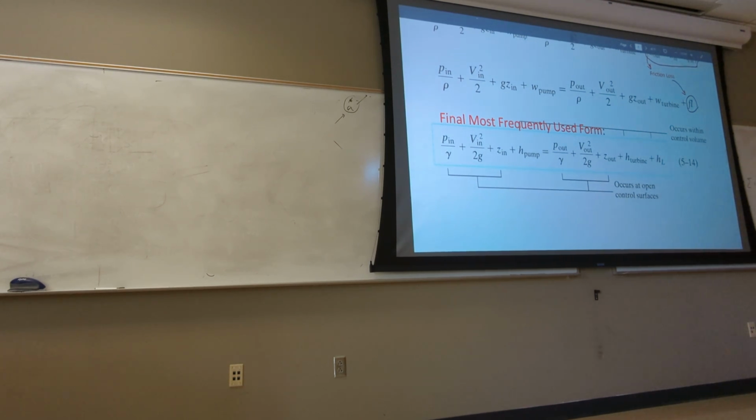You see, in fact, when we talk about friction, we're not talking about always loss. We also talk about the work coming from pump and turbine. Those all come from the surface friction of these devices. If you don't have friction, these devices don't work. You're not going to get any work out of the pump, or you don't generate any work from the fluid, because there is a friction. No rotation on the turbine blade. You see that? So this equation is an energy equation.